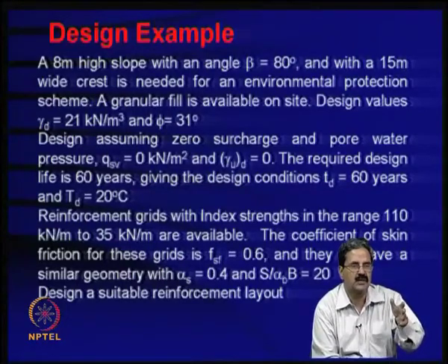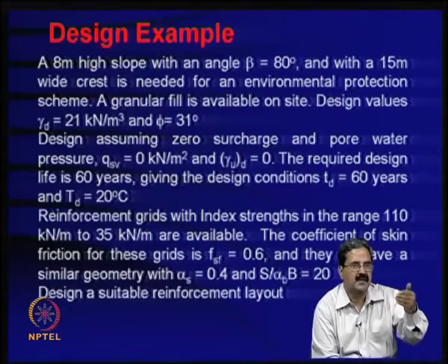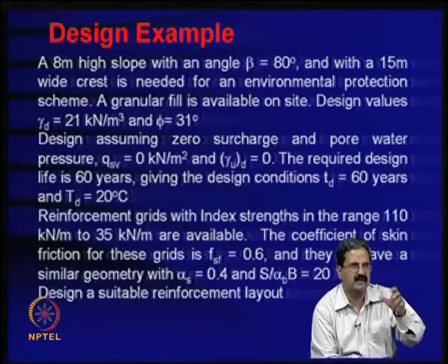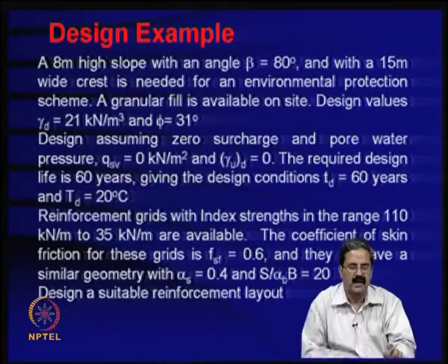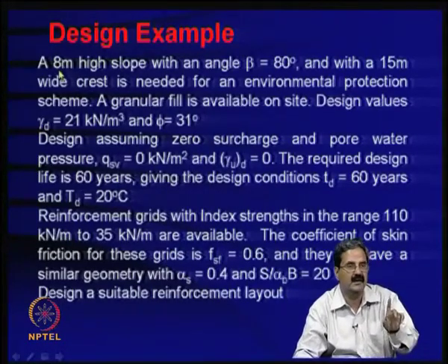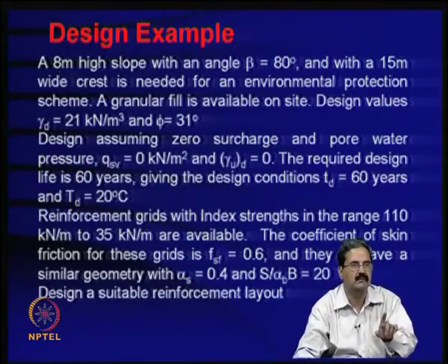So, once you do that, you will get that equivalent height, like nothing but it is like Q is 20 kPa, Q divided by then the bulk density, say for example 18, 20 by 18 will give you the extra height, say 1.1 or whatever. So, when you have a surcharge, you assume that it is only 8 meter slope, but design it for 8 plus 1.1, okay.